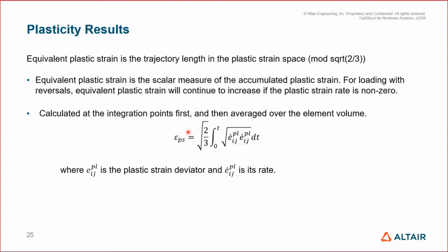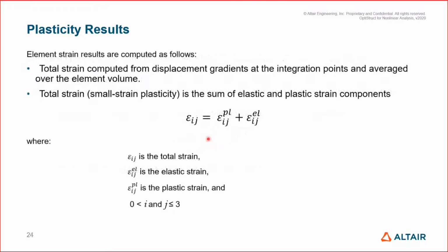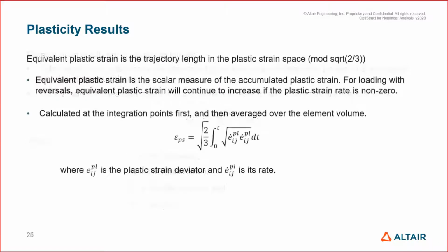It's calculated at the integration point and then averaged over the entire element volume. Some users use this to look at the plastic strain results rather than looking at the total strain here. You can look at both and see which one is more accurate compared to your testing.